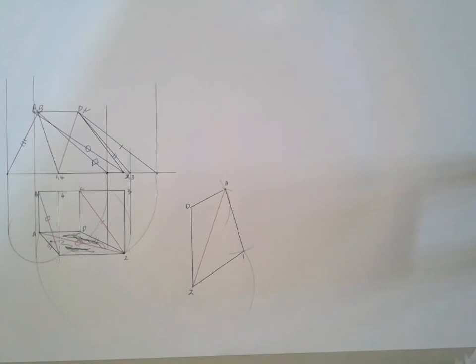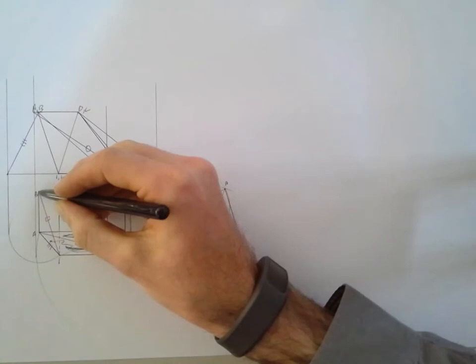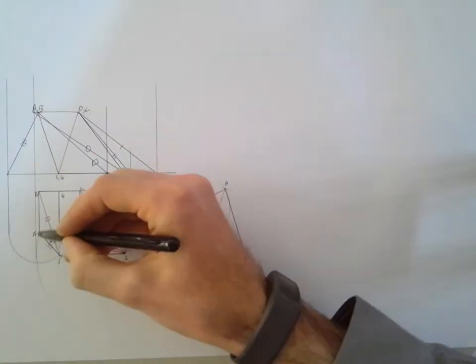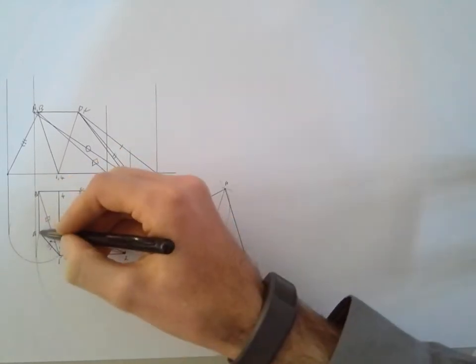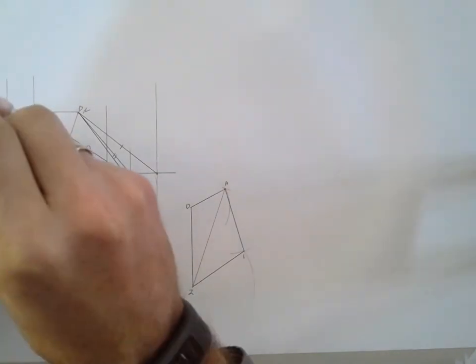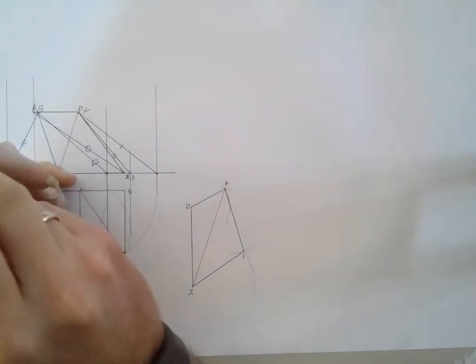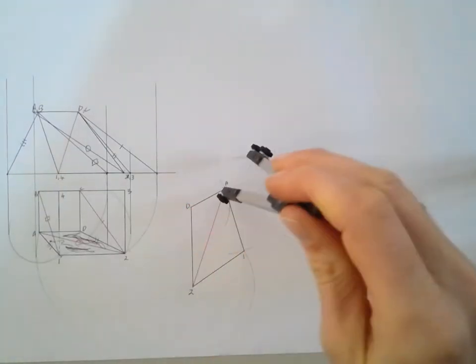Now as soon as I move around the corner, I'm now moving around to a face which is flattened away from you. So you have to remember that you are now moving to the triangle AB1. That triangle, okay? The triangle AB1. So I need the length of AB, which is a true length already, in my top view. So I can put my compass on that length, place it on point A, and make an arc.